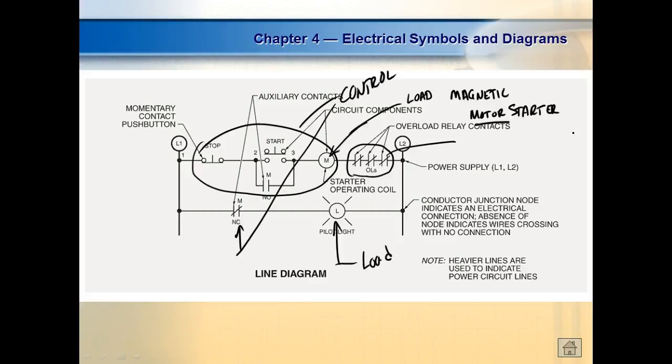So it means I got this motor out here. Now the motor's not in here, so we'll run into two sections. Out here we might have a motor, a 3-phase motor, by the way. And let's say this thing's rated at 10 amps. You understand that? Which would be a pretty good deal of horsepower, isn't it? So how much would it pull when we tried to start it? This would be the run current. How much would it pull generically when we tried to start it? Up to 60 to 80 amps.